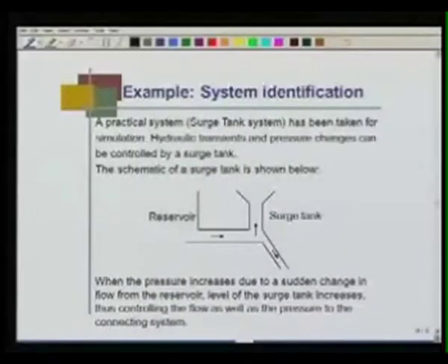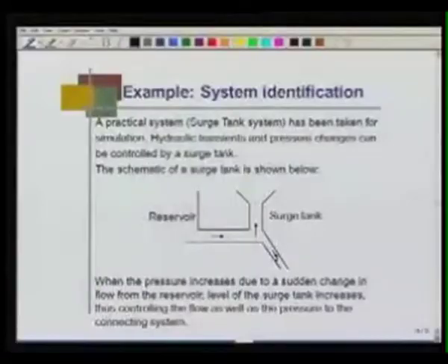And where the turbines have to move at a specific speed. Okay. So, the flow rate here has to be constant. So, if in this reservoir the water level suddenly increases and suddenly decreases, then this flow rate will be affected. So, to maintain this flow rate constant, the surge tank is used. So, whatever the disturbance in this reservoir level, that can be controlled using a surge tank. Whatever the extra pressure you have, this extra flow can be pushed to the surge tank.